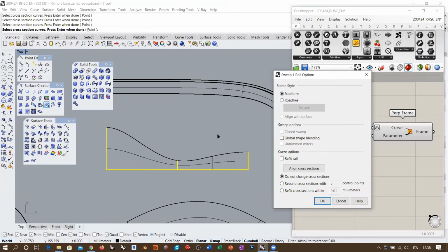Well, not exactly like an interpolated curve, because if this was an interpolated curve, which is this one, this curve should start from here, point directly in this direction here, and then go and end like this. You see that there is some curvature here. That means that this cross section converts into this one not with a constant speed. So this interpolation is slower on the first part, faster on the center part, and slower towards the end of this interpolation, this morphing. And the same happens between this second cross section and this third one.